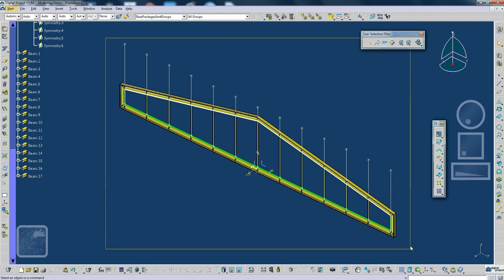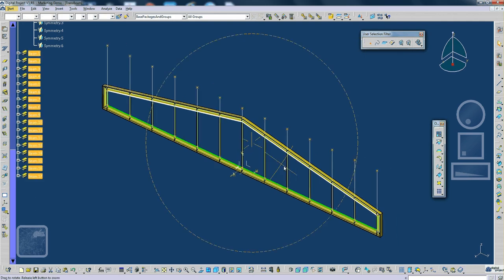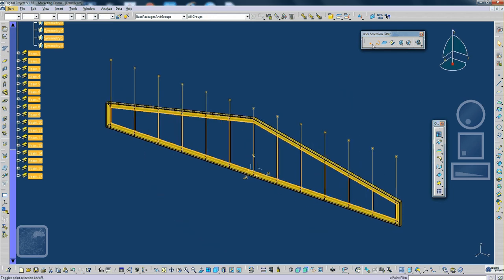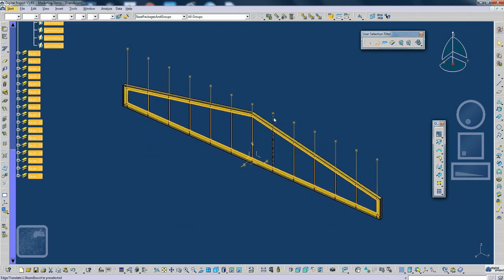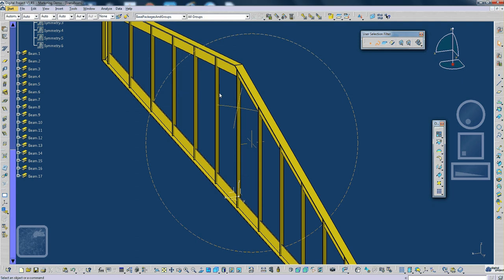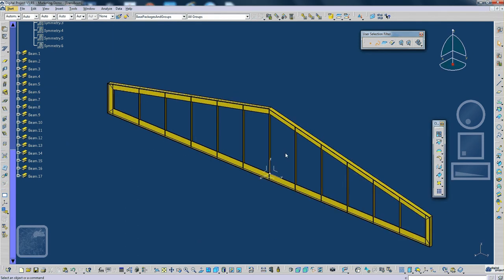So if I click a point and make a frame selection, I only select the point. If I add a curve, I make it again, so you select only the point and the curve. And now you can just press Ctrl H to hide all the wireframes, and you will see only the solid.